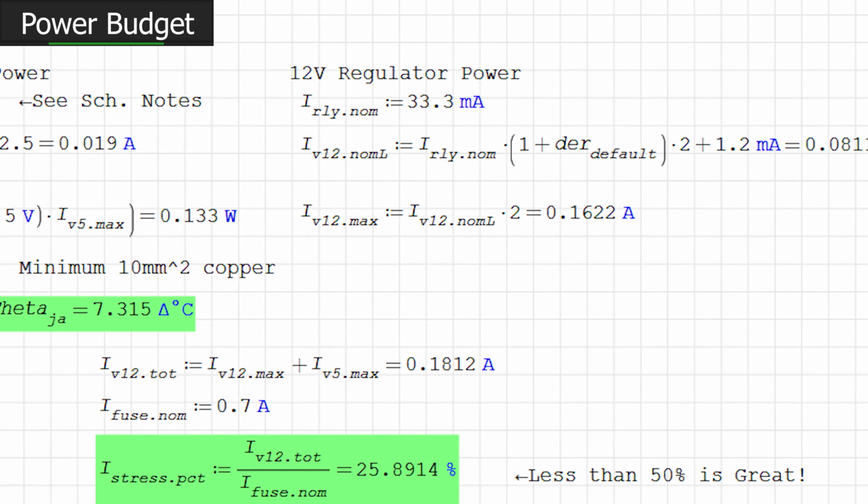Oh yes! The meaty temperature tolerance analysis. Good for the soul. So I started by gathering some critical tolerances from the datasheets of critical components: 1% resistors, 4% error from the voltage regulator, comparator input offset voltage, and some tolerance from the 8495 thermocouple monitor. Our analysis begins by combining the random error due to the 1% tolerance on the resistors using the RSS method. These should be relatively random errors, though maybe lot by lot they tend to skew together, so 2 resistors, whatever. We're going to assume them random.